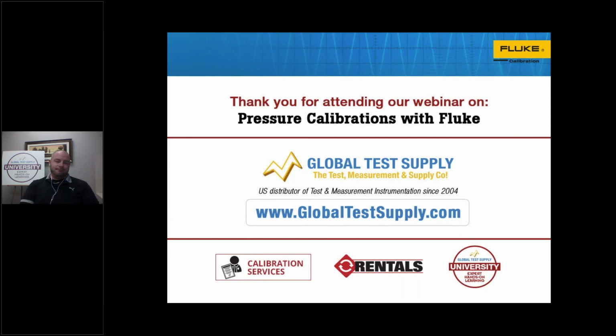That's a good question. It comes down to the way that the equipment is specified. The overall accuracy can be specified in so many different ways, and it's typically done to make equipment look good on paper. It's what we call banner specs. When you dive into the actual calibration accuracies, you'll find that there's two typical ways that they get specified. One is percent of full scale, and the other is what they call percent of reading.